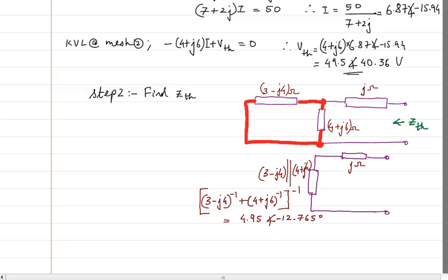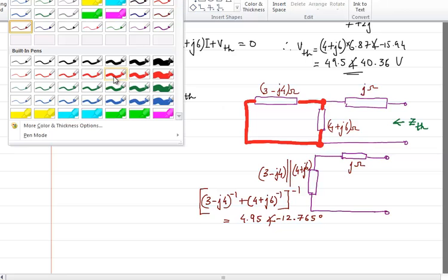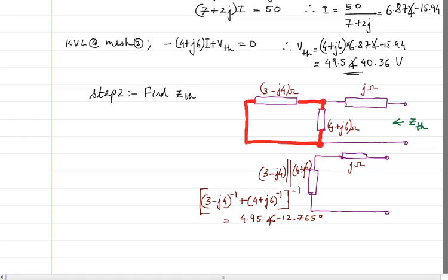How is it in series with J ohms? Again, for explaining, J ohm has two terminals, one is this one and the second is this one, whereas this particular element has one terminal here and the second terminal here. Okay, so when two elements are having a common node and there is no third node coming out from that, then both these elements are going to be in series.